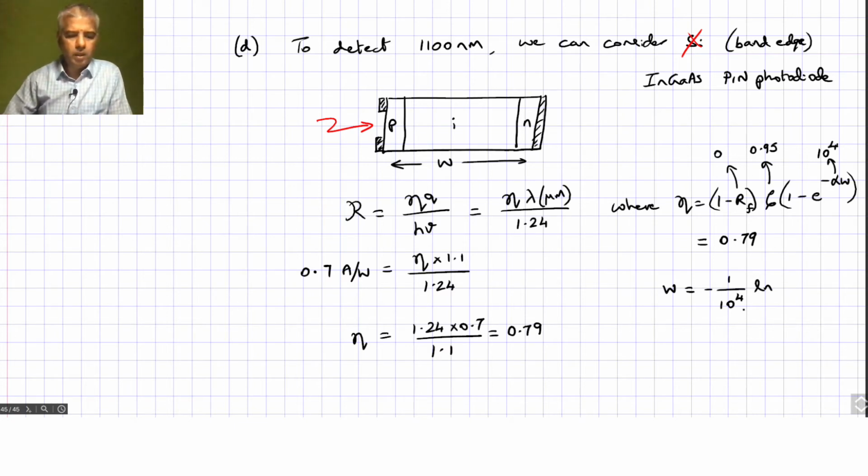So, that is actually... and there's going to be a 1 minus factor. So, that will basically be ln of 0.17, and this is in centimeter because alpha is expressed in terms of centimeter. So, 1 over 10 power 4 centimeter is micron. You can just evaluate this, it will work out to be 1.78 micron.